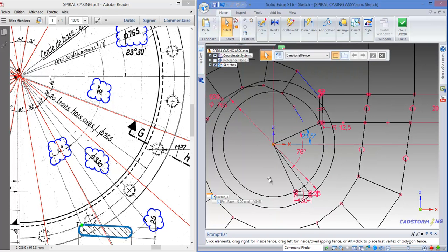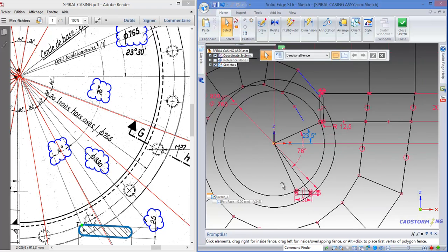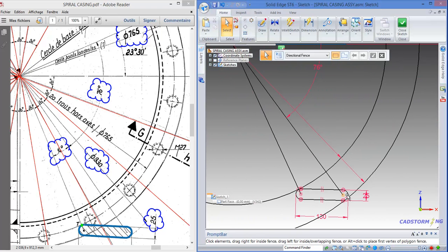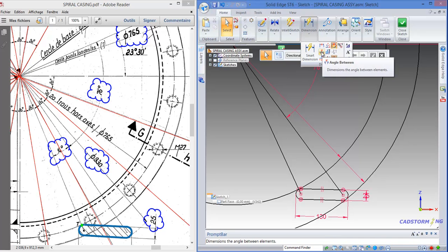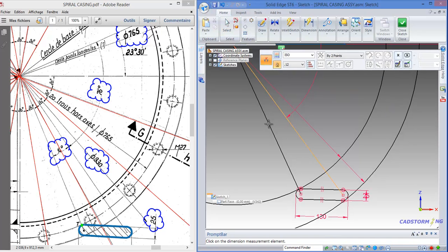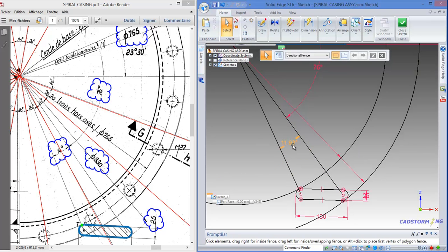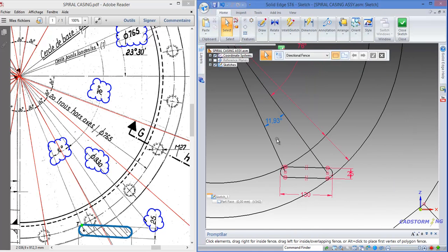Okay, but we have a problem, because as you can see, the deflector geometry is fully defined, but we haven't yet created this dimension. That means that something is out of place. We have to figure this out. Okay, so we will add the dimension first, angle between this line and this other one. The dimension is blue, obviously it is a driven dimension.